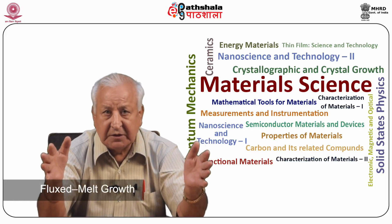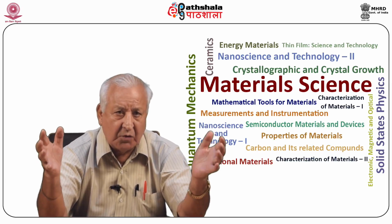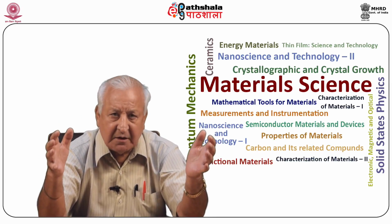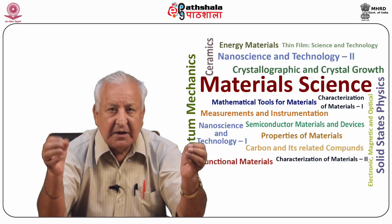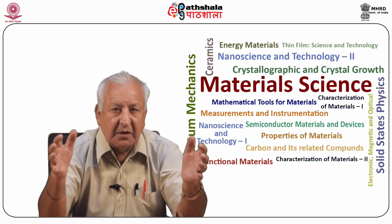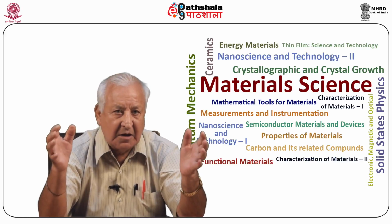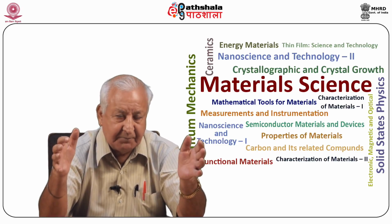Flux melt growth is a method by which a wide range of crystals may be grown with the minimum equipment and information. Components of the material desired as single crystals, usually a simple or complex oxide or fluoride, are dissolved in flux or solvent.